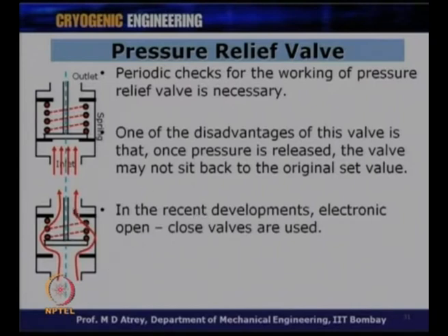One should see to it that some weekly tests are conducted to ensure that the relief valve opens at the same pressure all the time. Alright, so the pressure set value will not change even if the valve opens many times, and this is what one should do in having periodic checks.